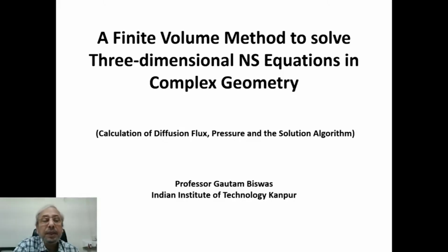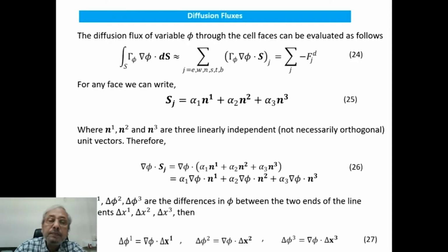Good morning, everybody. Today we will continue with our finite volume method to solve three-dimensional Navier-Stokes equations in complex geometry. In the last lecture, we discussed the important geometrical parameters and the procedure of calculating convective fluxes. So today we will discuss the diffusive fluxes.